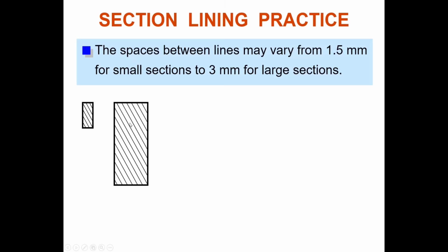Actually, you don't have to measure every single line. So do I need to measure them? No. Because this section is not drawn by hand, guys. Like I showed you, sketching is by hand, but here it's back to your tools. Use your triangle or ruler to make your section line. Actually, the angle of your section line is not always 45. It depends on the angle. This one is more like 60 degrees. But the angle of your section line cannot be vertical or horizontal. The angle is between 30 and 60.